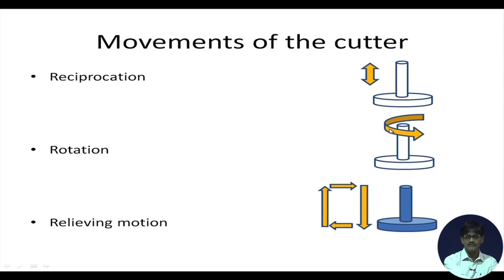In addition to that, as we have noticed, the cutter also has rotation, because we have to create a situation in which, as if cutter and the workpiece are already formed gears and they are rotating against each other as if they are rolling together. We are creating that condition. So, in that case, if the cutter removes all the material it meets on its way, it will ultimately give rise to a completely machined gear out of the blank.